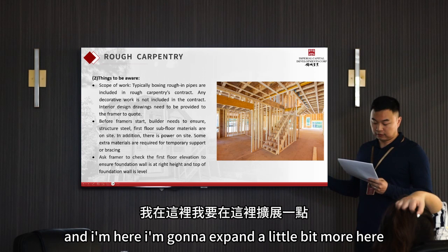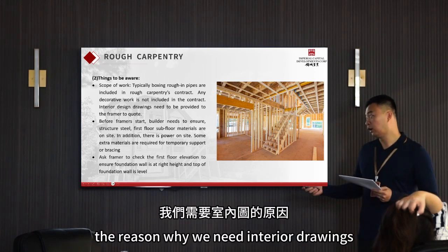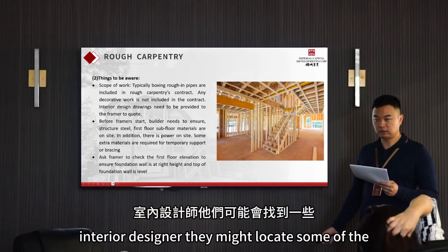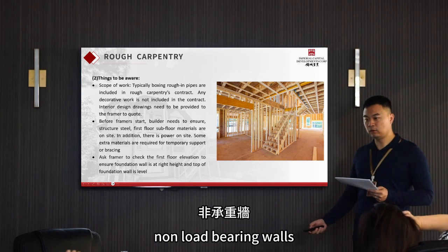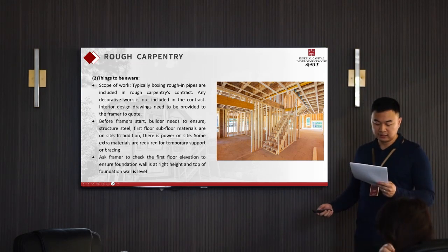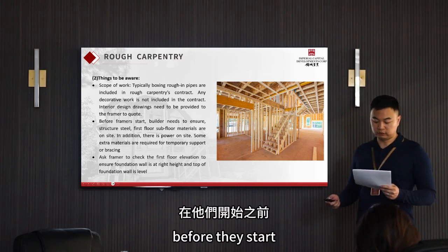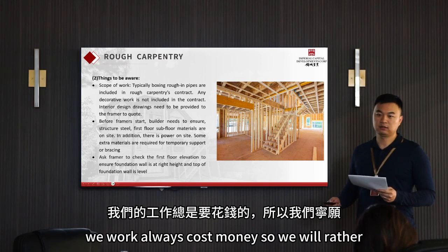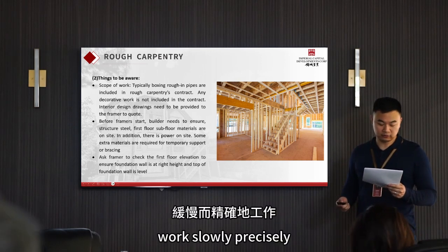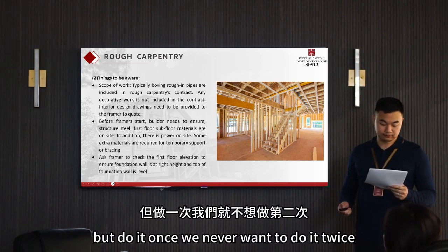And I'm going to expand a little bit more here. The reason why we need interior drawings before the framer starts. Sometimes interior designer, they might locate some of the non-load bearing walls. They might want to change the floor layout a little bit, and those informations needs to give to the framer before they start. Rework always costs money, so we would rather work slowly, precisely, but do it once. We never want to do it twice.